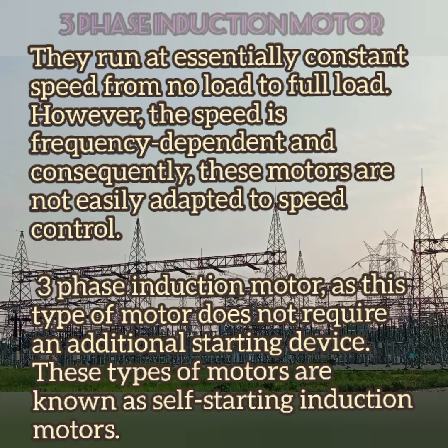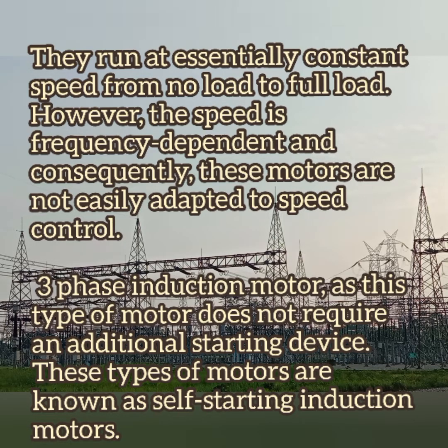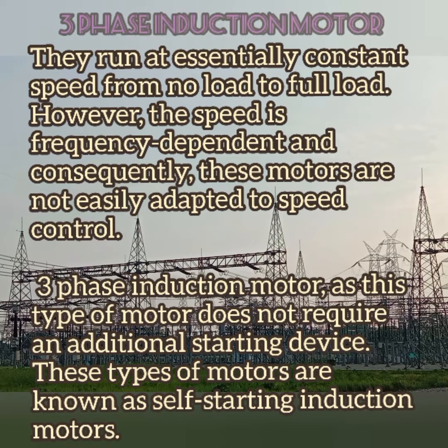Then this three-phase induction motor doesn't require any additional starting drives. As you saw in the previous video, a single-phase induction motor requires one additional starting drive for self-starting. In three-phase we don't require that kind of self-starting device. It is automatically self-starting.